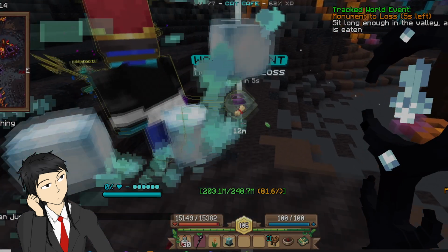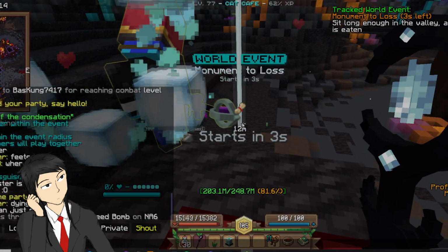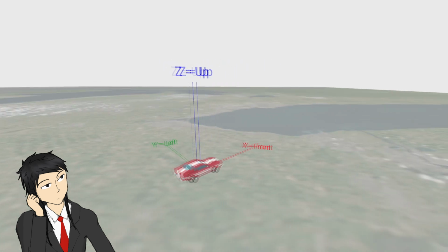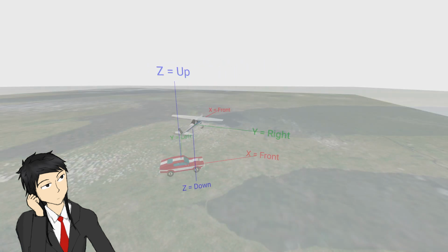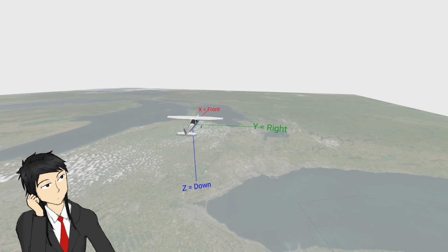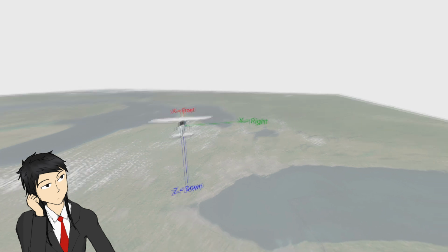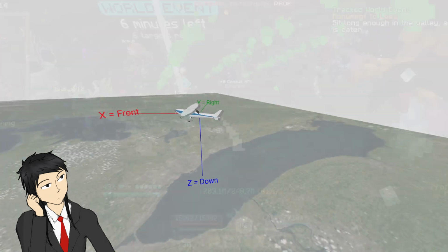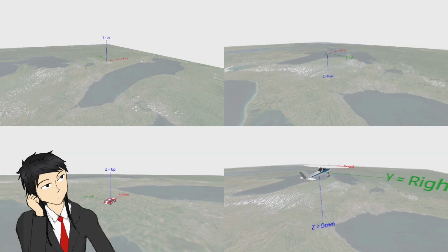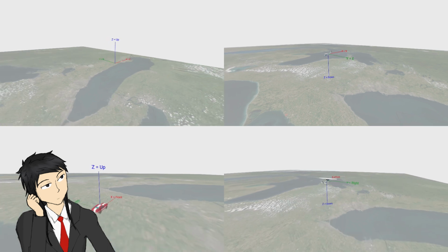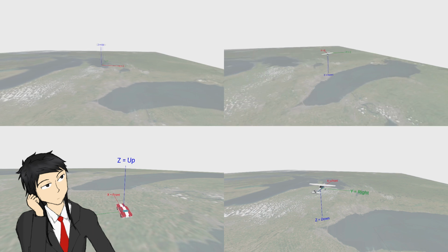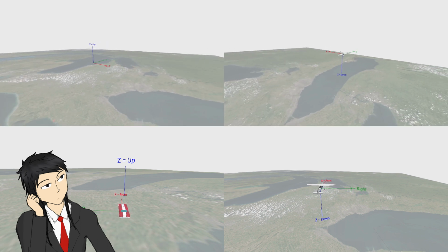But then we can also talk about coordinates relative to a vehicle. The navigation and control system in a land vehicle use front, left, up. Meanwhile, ships and planes use front, right, down. So you can see that between these two pairs of systems, either X and Y are exchanged or Y is flipped, such that there's consistency in that all of these are right-handed.